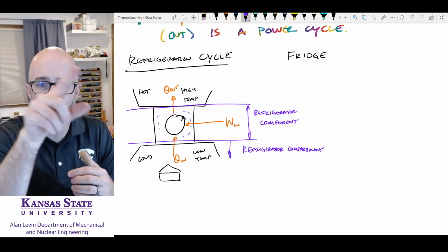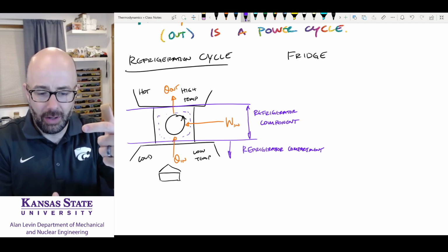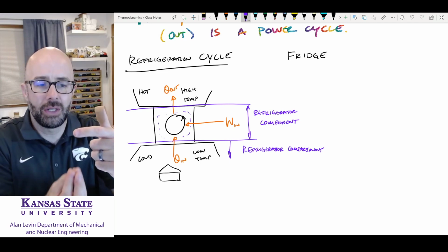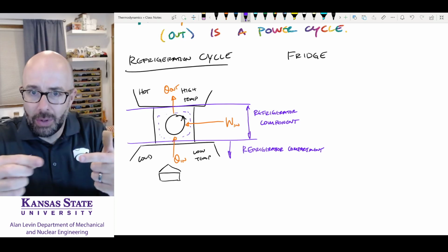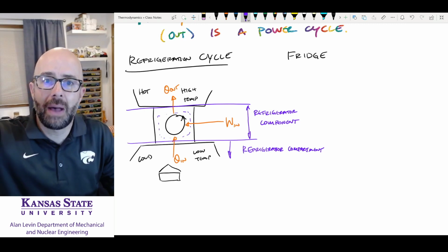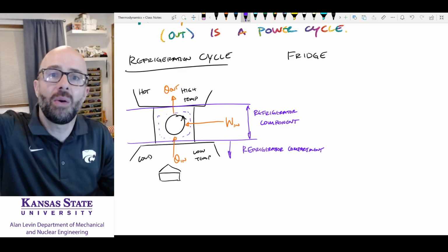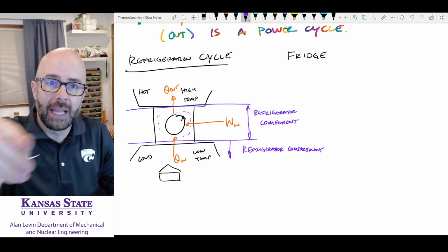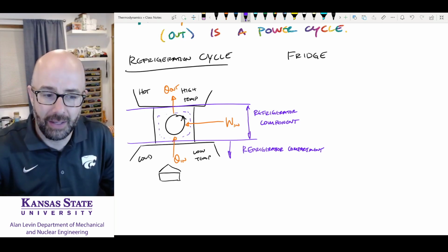And that cold refrigerant is coming into the cold compartment, and your hot pie is going to put heat into that refrigerant and warm that refrigerant up, and it's going to keep going through the cycle. Now it's a little bit warmer. It's going to go back through the cycle, and it's going to then expel that heat out to the back of your refrigerator and come back in and try to get cold again. So it's going through this process like this.